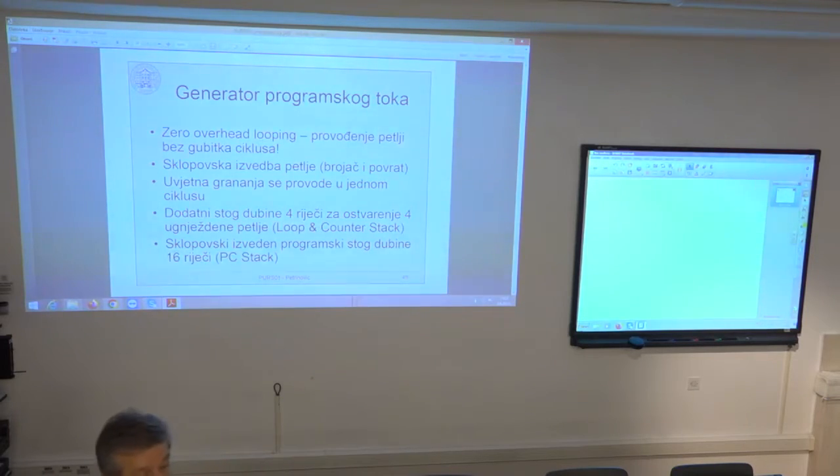have any memory access, because everything that is done normally using some kind of stack is inefficient, because you have to fetch the data value from stack, and that is actually fetched from memory. You have to take the value from memory, and it takes at least 1 cycle to read this value from memory. But if this value is in internal register of the architecture, it can be taken from this register directly without any fetch. So you don't have this overhead of fetching the values from the stack.